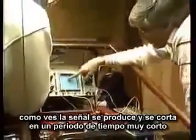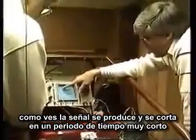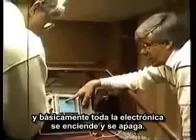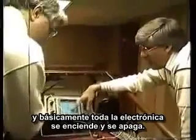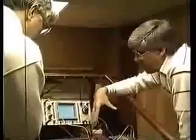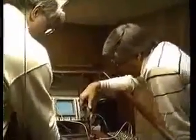You see, as long as this switches up to high and low with very sharp rise time and fall time, you're not dissipating any energy. Basically, all the electronics either turns on or turns off. So power-wise, this is the most efficient because it is digital. It's not sitting as an analog device.